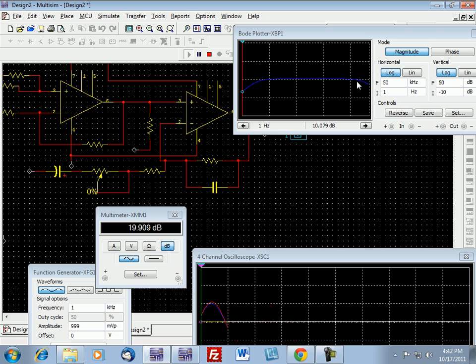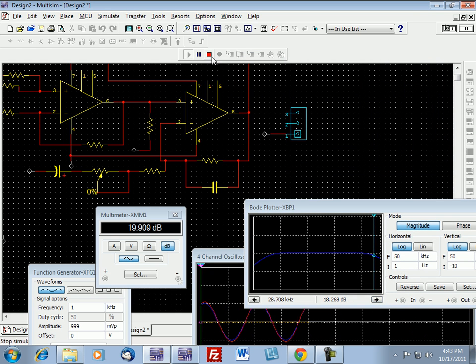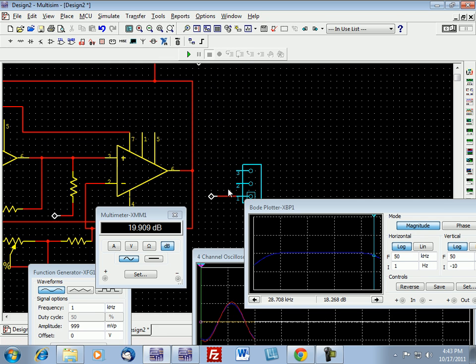So as you can see here, it rolled off after we installed the capacitor. You see, we start to get it after 19, 20. Now it started rolling off after 21, which is what we want. Now the preamp is done. It checked out well.